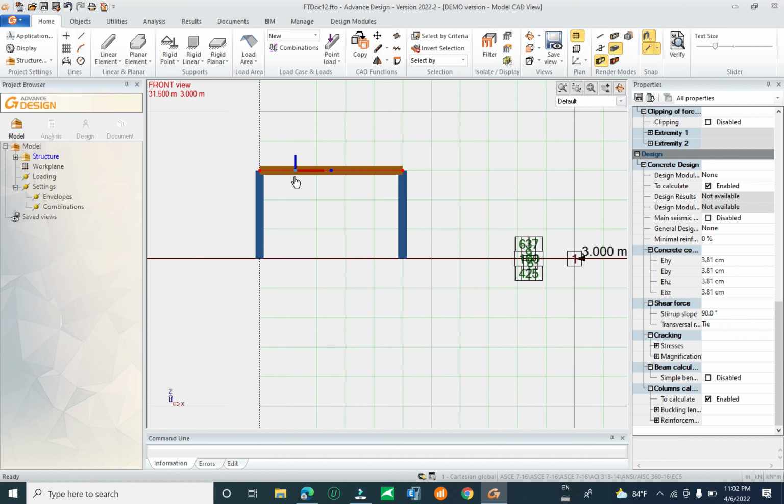Now we want to design a column, we call it beam. You see for the bending, and a little normal force, but the column we design differently from the beam. In this case you have to click on beam, and you have to untick the column.